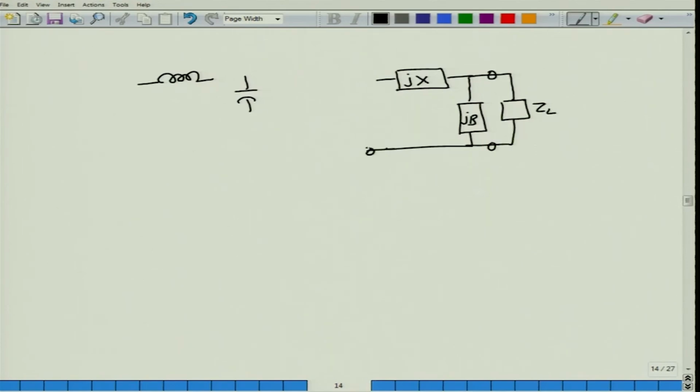So this is how the matching network would look. Let me just delineate this matching network in terms of dashed lines. This is where the network is going, and let us say this is some R0, the reference load that you are trying to match, and ZL is of course the load. In many cases this ZL would be real at these low frequencies, so it would be RL and this would be R0. In many cases this R0 is actually equal to the resistance or internal resistance of the generator RG itself. So this is an L section in which the admittance part comes first, and then you have a series reactance. So you have a susceptance here and a series reactance.